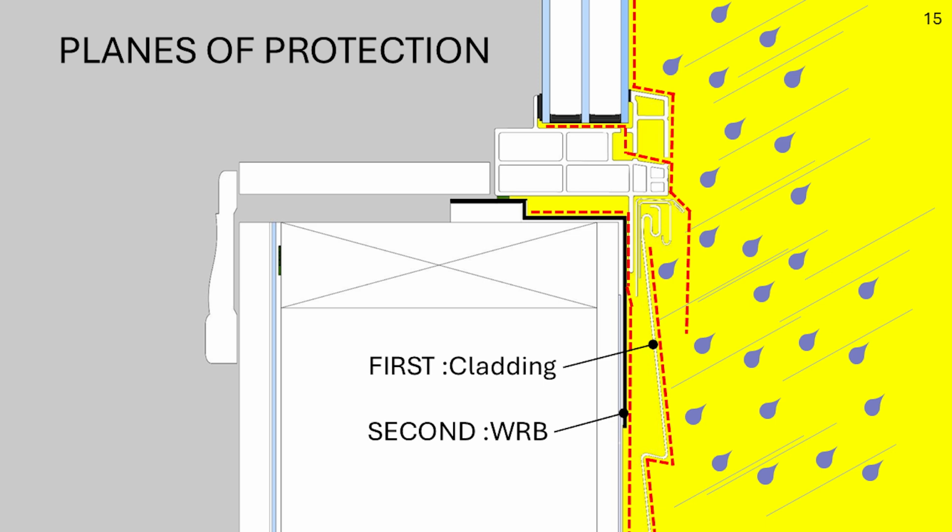Now, in the window itself, if water is getting in here and the wind is blowing and moving it away so this seal opens up a little bit, whatever water gets into this opening, we're draining that out through the weep in the window because we know water's going to get in there.